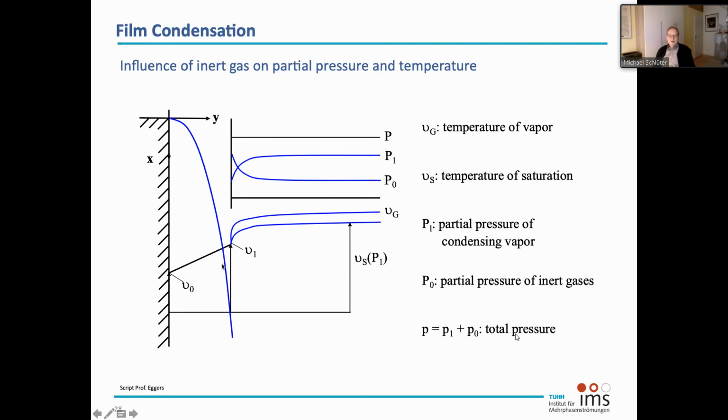So what can you do about non-condensable gases? It sounds strange, but unfortunately it's true. You have to open your heat exchanger from time to time to release some vapor, and with the vapor you release the non-condensable gases. Of course, you lose energy if you do that because you release steam, but it's better to release some energy by releasing steam than creating a barrier against heat transfer by non-condensable gases. This might sometimes be a problem in heat transfer processes.